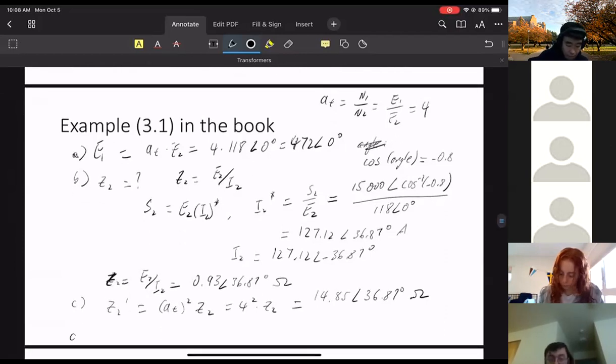And for part B, this is the ideal transformer, so the power supplied by the source is exactly the power consumed by the load. So S1 equals S2. The power computation is easy; we don't need to do anything. Really, for this question, the tricky thing is how you compute the impedance. Generally the safest way to compute impedance is to go through the power route: write out the power equation, S equals E times I conjugate, compute the current conjugate, take out the conjugate, and compute the current.